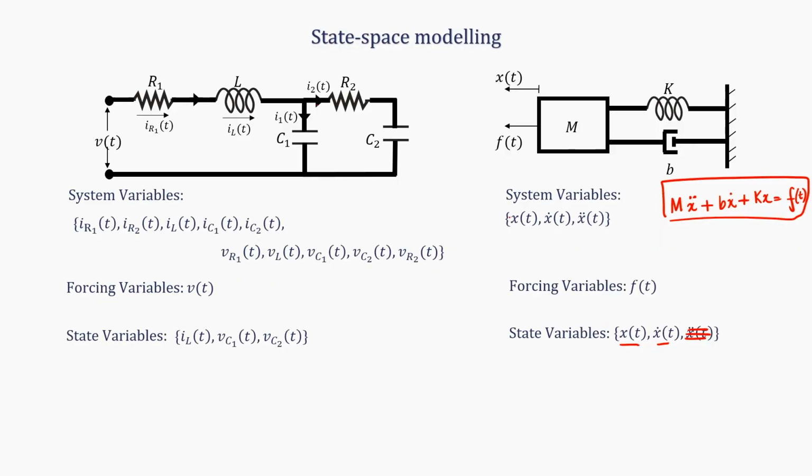Are these the only state variables? No, you see, remember if I say it in the definition, you can come up with a different state variable also. This also will become a state variable. This is also a state variable, although it does not have any physical meaning, x plus x dot and x minus x dot, because you cannot write x plus x dot in terms of x minus x dot. Similarly, you cannot write x minus x dot in terms of x plus x dot. So, they are linearly independent anyways, and we have 2 elements. So, these will also become your state variables. So, state variables are not unique, okay, but the number of state variables will be unique.